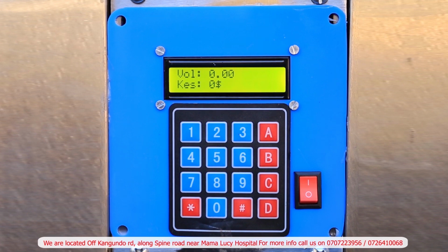The other option is setting the administration password. Therefore, you scroll down by still pressing the letter D to option number 4 for setting password. You key in number 4. Then you are required to key in your new password. The current password was 1234. Let's say you change it to 4321. Therefore, you'll key in 4321, and then press letter A to confirm or change that password.